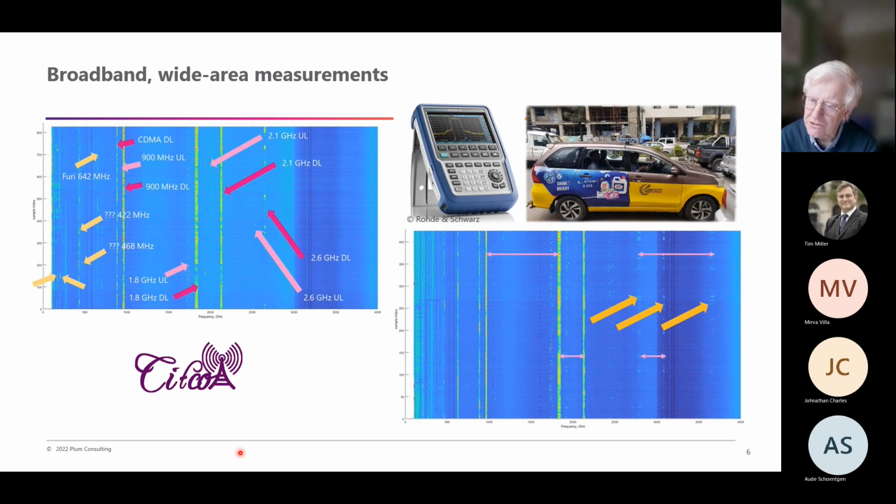The signals you see here are just artifacts produced by the spectrum analyzer when it encounters very strong signals at lower frequencies. And this generates these spurious signals. So the answer to this is that in those situations, you should put more attenuation. You should lower the sensitivity of the equipment to stop the overload.